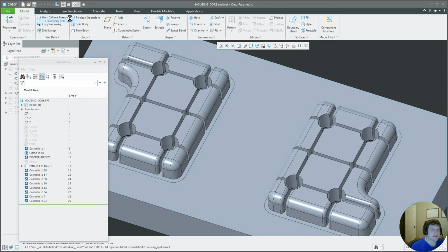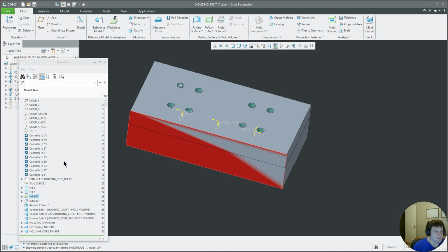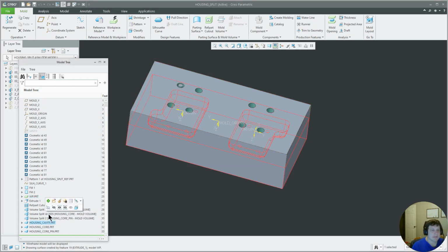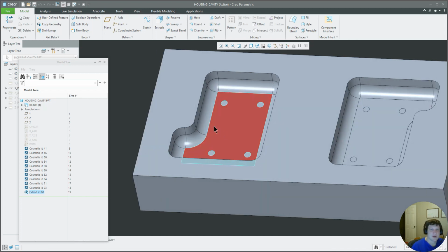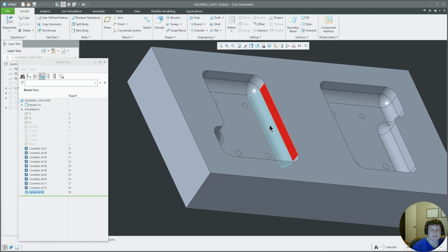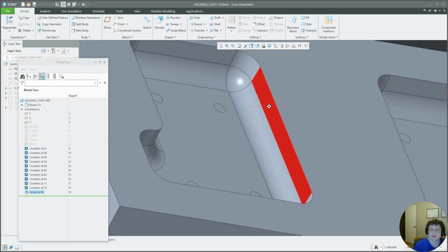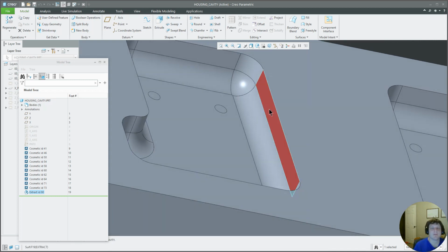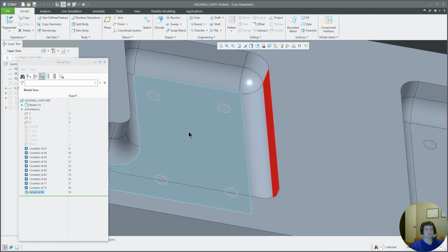or the cavity block, as I call it in this split here, where this is the cosmetic surface. We don't really want to put a gate blemish right here on this cosmetic surface. We could, if the customer wanted us to. That would actually be almost an easier place to put a gate, but we don't have to.